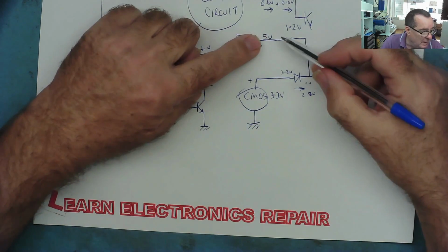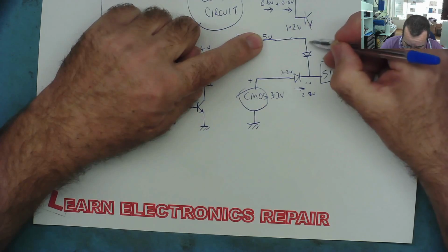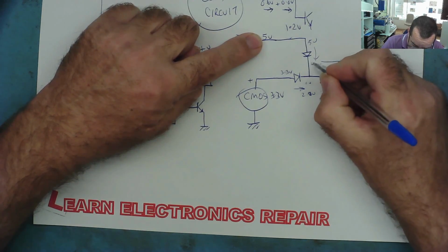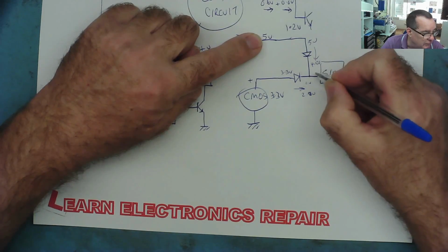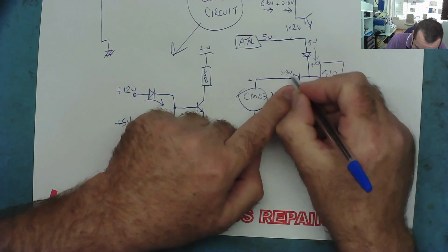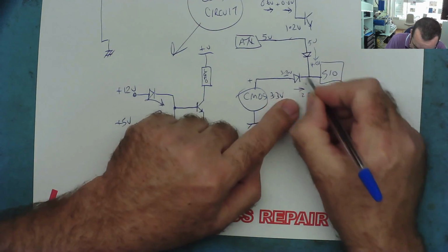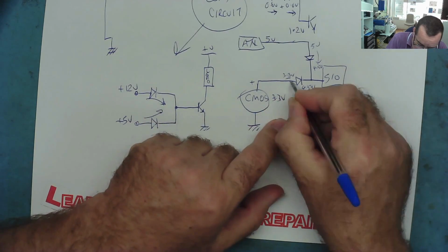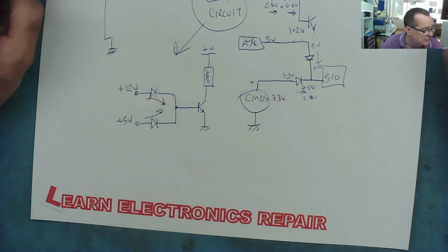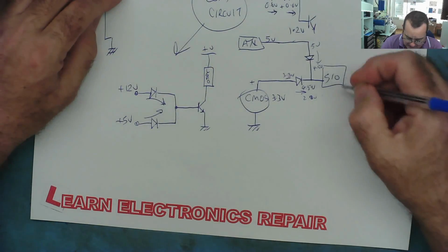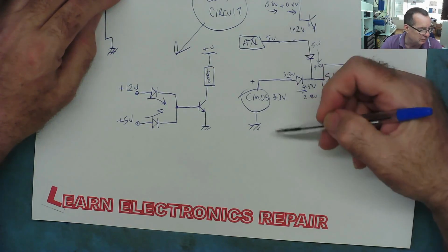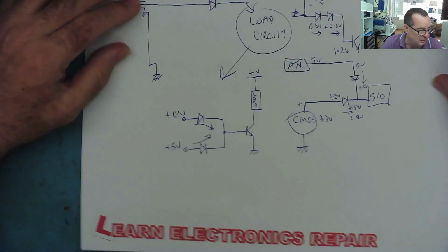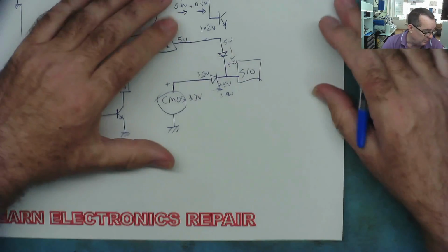When this turns on, you've now got 5 volts here, powering here. This end is now about 4.5 volts, half a volt's drop. This diode still has 3.3 volts on this end, but it now has 4.5 volts on this end. So this is higher than this, and it can't conduct; it's reverse biased. So automatically, the SIO chip will power from the ATX and not the battery, but the ATX 5 volts never gets into the battery. So that's another good one, and these are common circuits you'll find.